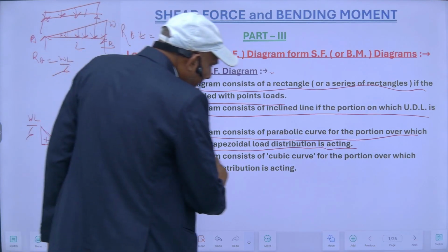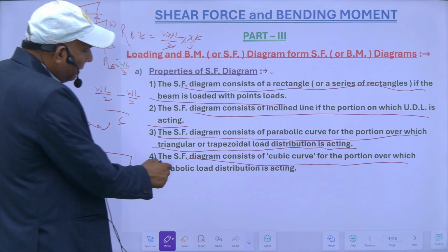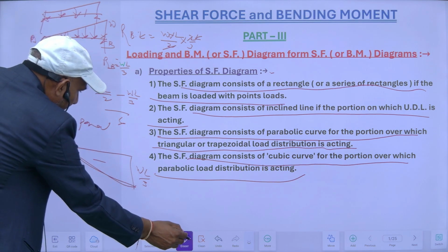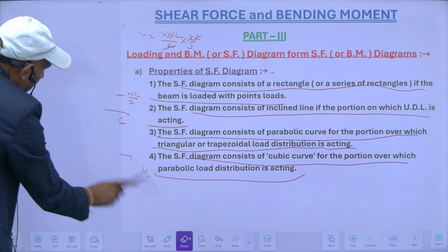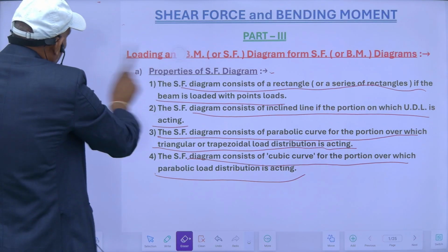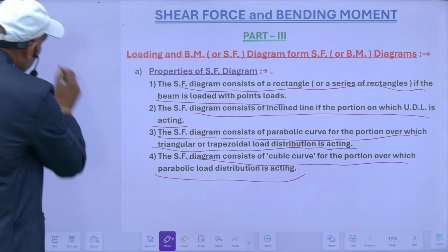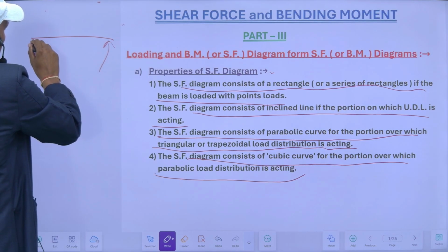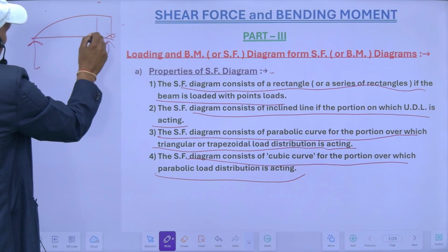And the shear force diagram will consist of a cubic curve for the portion for which the parabolic load distribution is acting. Suppose my loading is parabolic, like this. So this is my loading, it is parabolic.